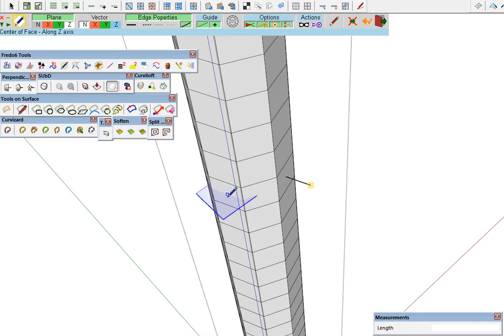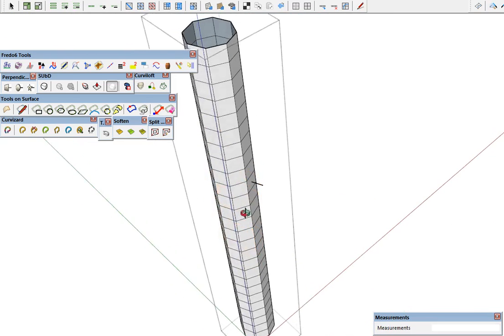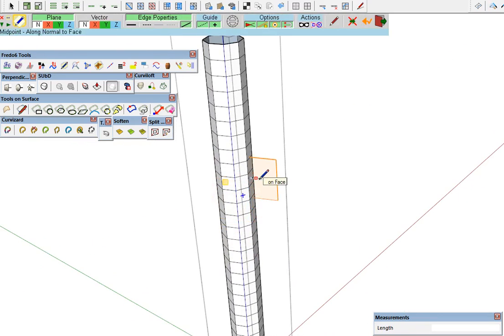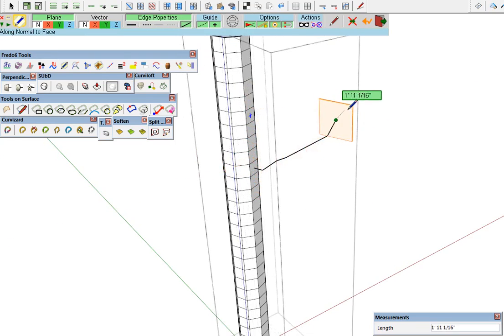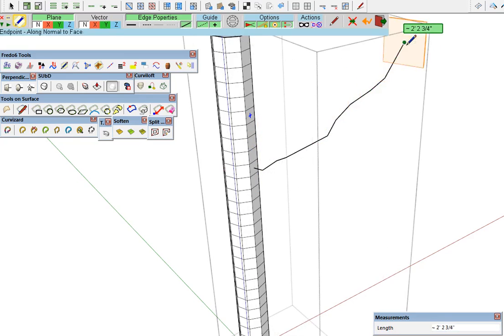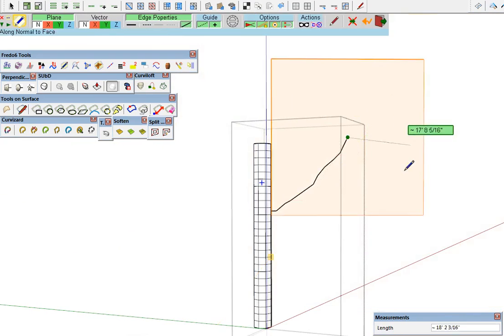What we're going to do is snap it over here. I'm going to hit Return, and we're going to get this work plane here, and that's just going to allow us to draw a collinear edge. It'll put the plane right in the middle of this set of faces. So we can come out here and make a bunch of clicks, and that's going to be our first branch.